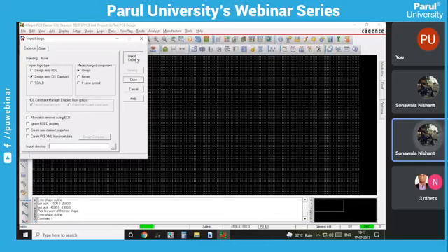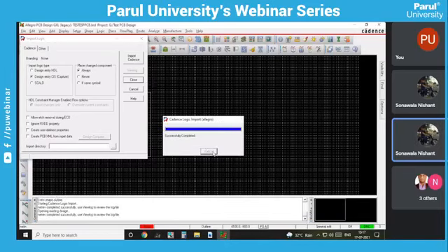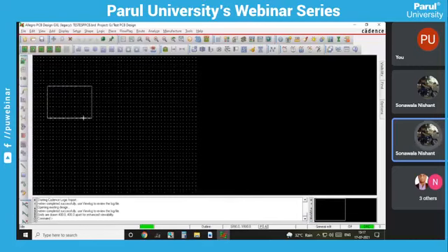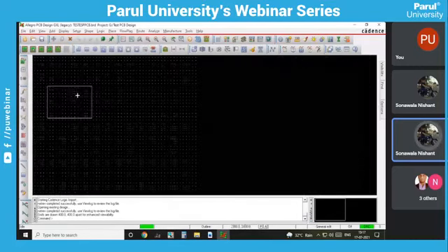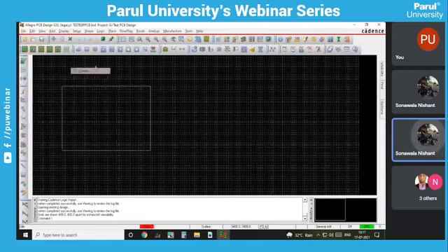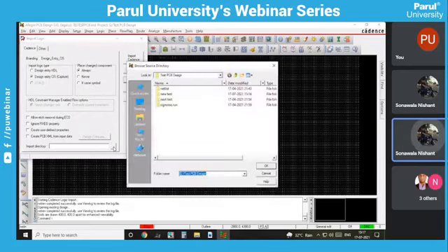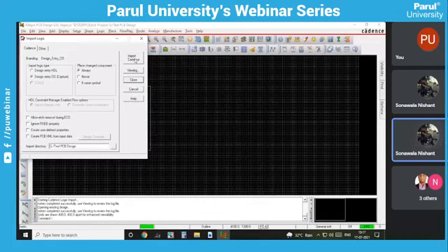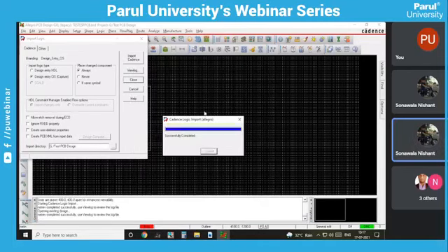Now import to Cadence. We have imported a component successfully, but where is it? Okay, so wrong placements. Go to import, again go to logic. Here we have to mention a directory. So directory and then import.